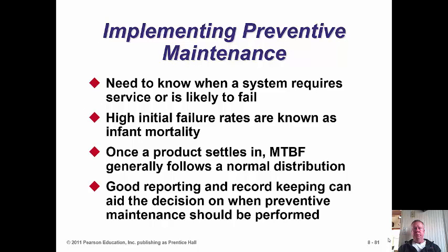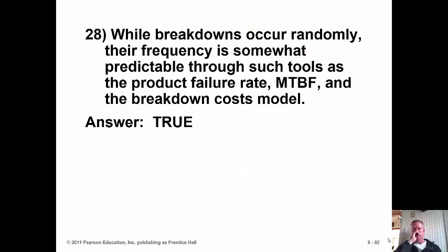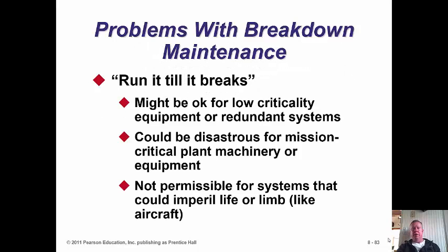Preventive maintenance. So yeah, it's based upon good engineering data. Infant mortality is mentioned in there. MTBF, mean time between failures. Yeah, and it's all based upon records. Product failure rate, MTBF, breakdown cost models. Again, it's even better to be done with continuous monitoring and predictive maintenance.